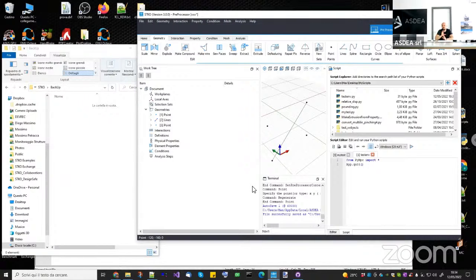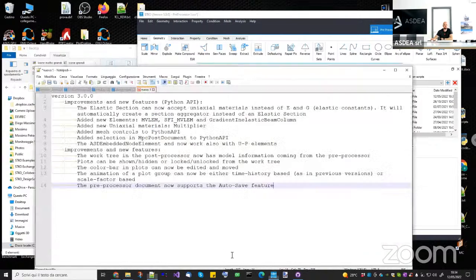And this habit will not work very nicely with the autosave feature, okay? So for the moment, you can do it, just remember to save your file many times. In the next version, we will create a backup file for every STKO instance, so there will not be any problem. Okay, so this is all for the backup file, for the autosave feature.